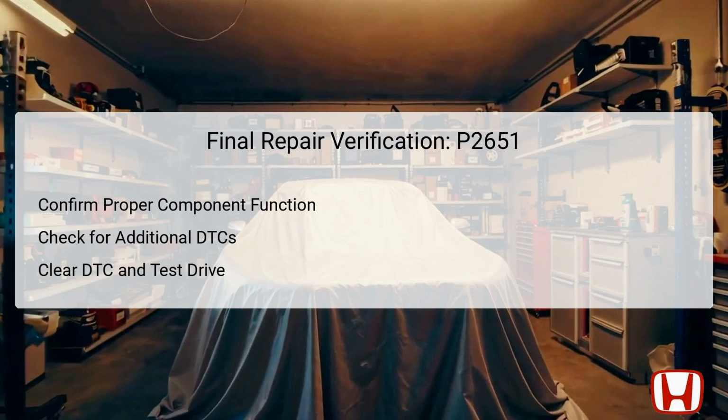After performing the necessary repairs or replacements based on the diagnostic process, the final repair verification stage is essential to ensure that the solution implemented has resolved the issue. First, you need to confirm that all components involved, namely the rocker arm oil pressure sensor, VTEC system oil passage, and rocker arm oil control valve are functioning as intended. Following this,